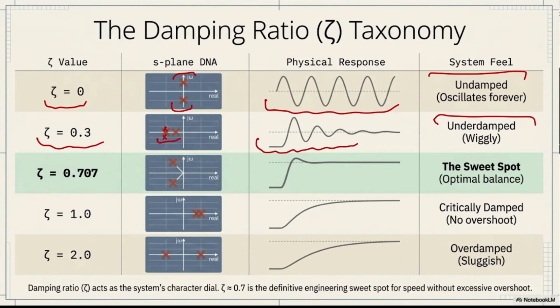On another point, we do have this damping ratio of 0.7, which is the sweet spot. Most of the time, we would like to have something like this. It means that I do have the real part and I do have the imaginary part, but both of them are considerable. It's not like the previous one, where we had the imaginary part that somehow we got rid of. That's why my poles were stuck to the real axis.